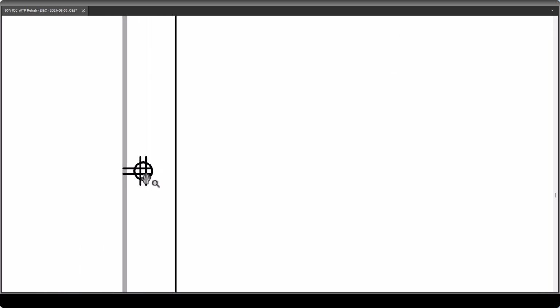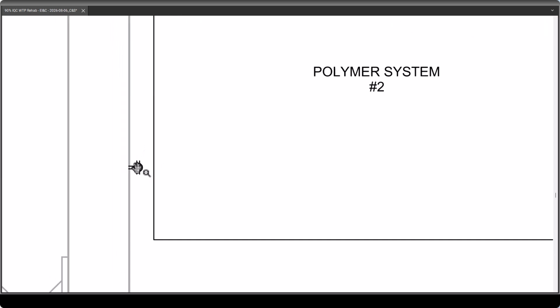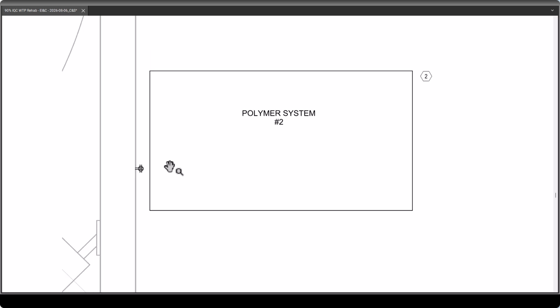This is my receptacle that lives in my model. You are showing it as new, which tells the contractor he should be installing it, but you could provide no information. You could turn it gray. You could hide it. You could do half a dozen other things. You could even say, provided by others, coordinate with the EC, something to that effect. Does that make sense? Yes.